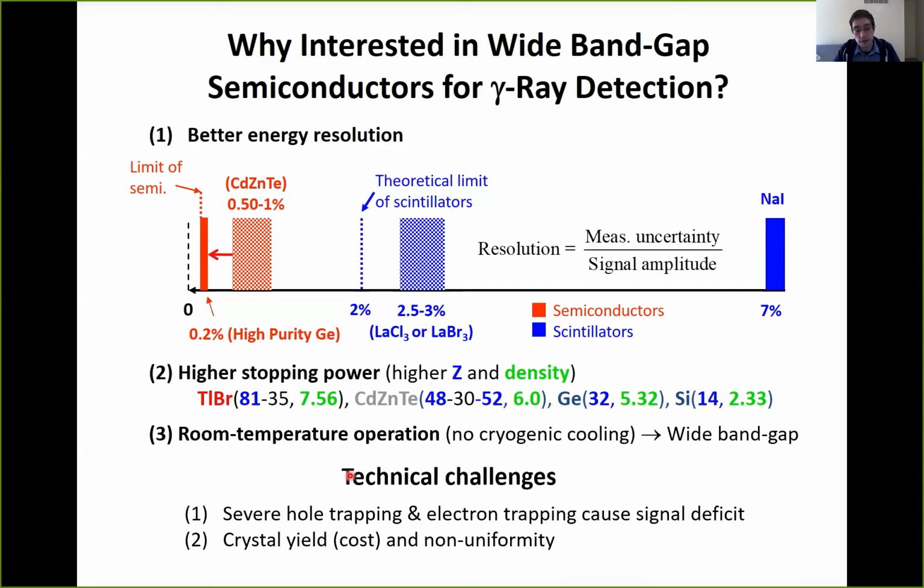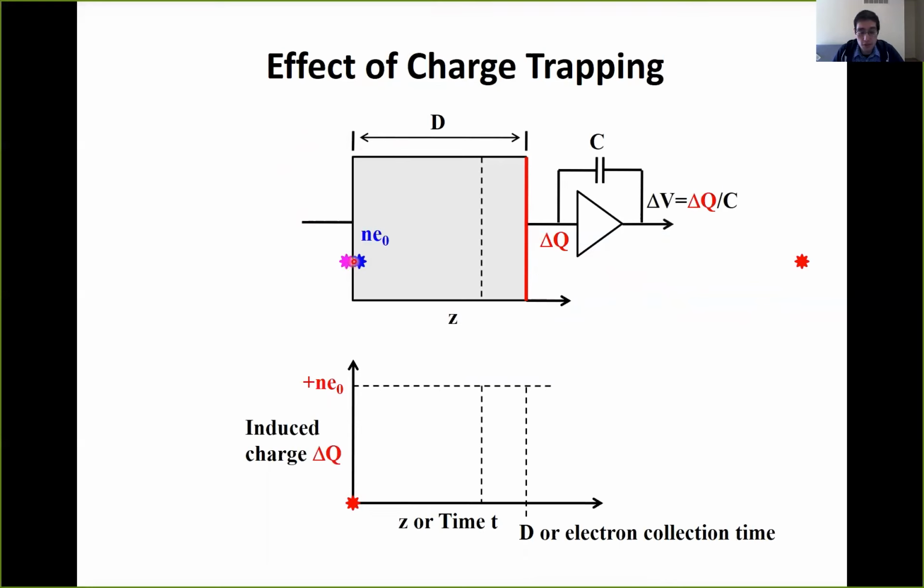How does the physics change? And this is what we're trying to see. When a gamma ray deposits some energy, the electron gets ejected. It will drift towards the anode, and it will induce a charge. This is some amplifier, so let's ignore this. And let's have some recorder somehow over in this logic circuitry. When the electron drifts, it induces some charge, right? The way you can see this is that there's a mirror charge moving in the opposite direction. The signal you would see if it drifts from the cathode to the anode is the full signal induced because it moves through the entire electric field.